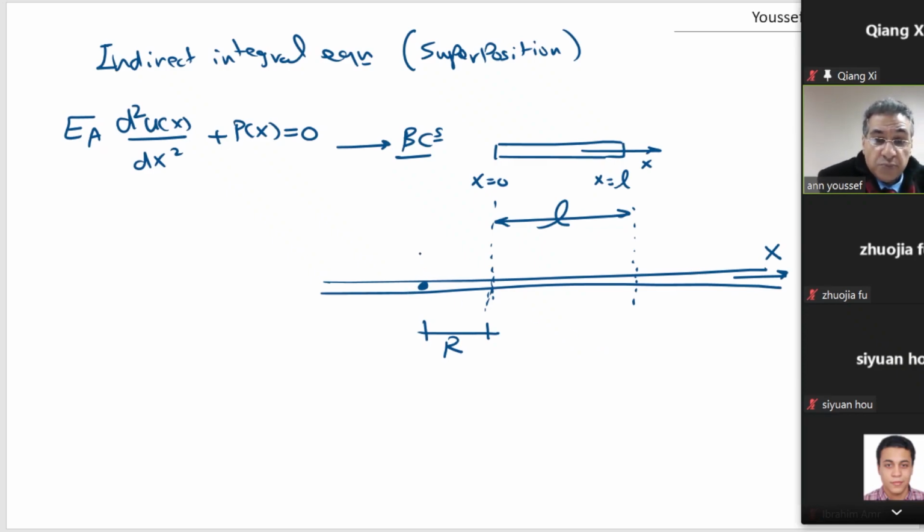I'm going to call this point xi1. So xi1 has a source load, something like a unit load. So the effect at any point x, for example, if I have a point here equal to x, this is just a general point, and x moves from x equal to 0 to x equal to L in the infinite beam. So the response at this point, I can write it like that.